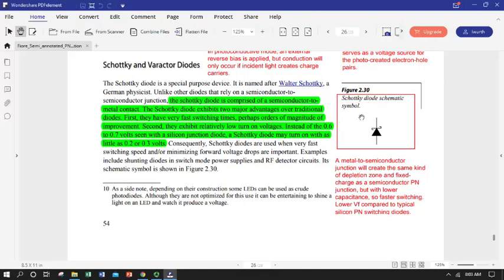And basically the way that works is the energy bands in the metal conductor, you've got that partially filled valence band, it'll actually bend up or down as you interface that with an N-type semiconductor, and it creates the same kind of voltage hill that we have at a PN junction, really, really similar. So it's going to have a one-way conduction, just the same as we do with our standard PN junction diode, but it operates faster because you've got metal on one side.